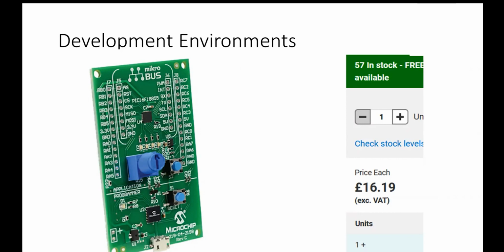But if you then take a file, something .hex, and drop it onto that drive, then that file will be sucked in by that microchip below the line and will be programmed into the chip on top. No more PICkit 4s or PICkit 3s or ICD 4s or any of that stuff. All you need is the wee board and a micro lead. And it's very, very simple.